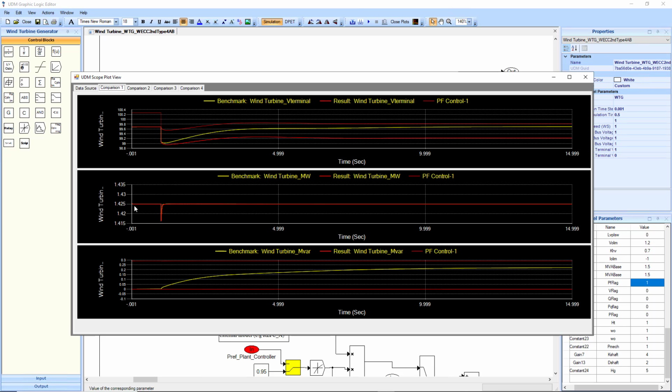As you can see, if we want to keep the active power constant, we need to start providing some reactive power, as you can see here in the dark red plot. Therefore, since we are injecting more reactive power, the actual terminal voltage is slightly higher. And of course, once we apply the voltage impact disturbance in transient stability, we are not controlling voltage, as we are controlling the power factor. We are keeping the power factor constant.